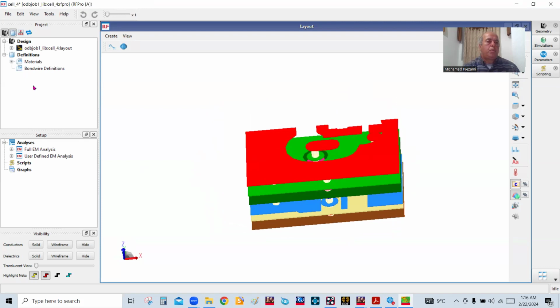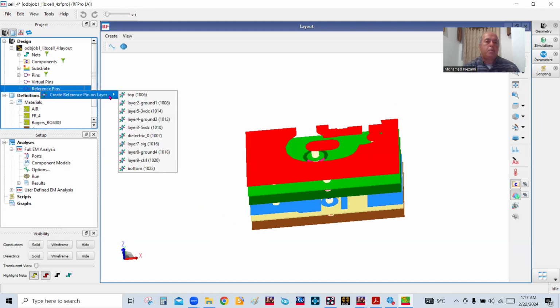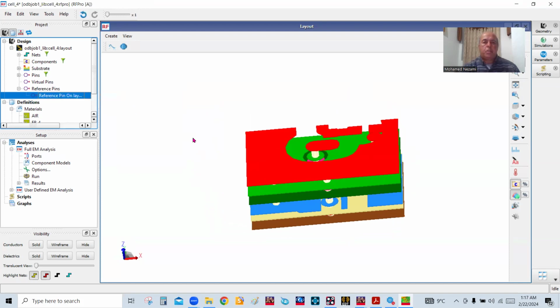And what we want to do first is take the inputs into the EM simulator. Well, let's make a reference plane. I'm still going to reference the bottom, the first ground layer, but it'll take care of itself because the vias interconnect all the ground sublayers. All the sublayers that are ground are basically hardwired using vias.